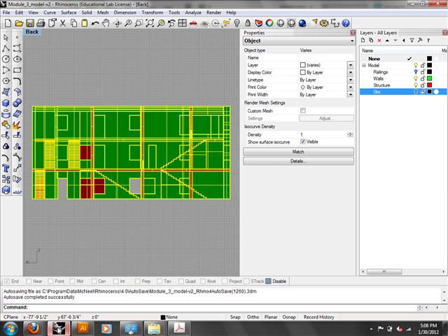And Make2D has its own problems, as I think you guys know. Some of the lines don't come in that you think are going to. My class had a lot of problems with select visible, some of the people I talked to. Again, you just have to do select all. That'll take care of it. Or strategically turn things off so that when you do select all, it doesn't make too many lines. I don't have any really good answers for that kind of thing.